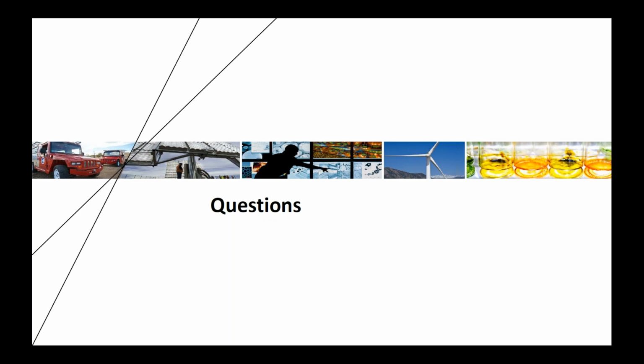I can take that. So we didn't see any downside. I think the only climates where you would see a downside would be in dry climates, where if you don't run with that blower off delay, you're going to lose some of your cooling you've done from ductwork that's in unconditioned space. So that's a fairly limited subset.